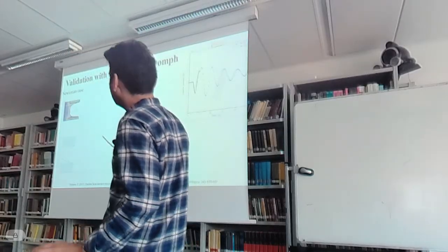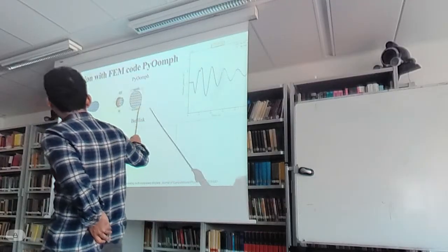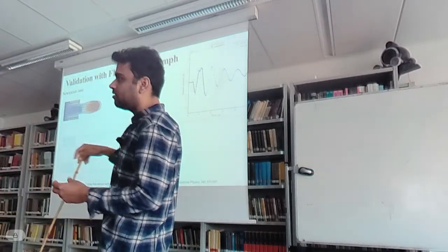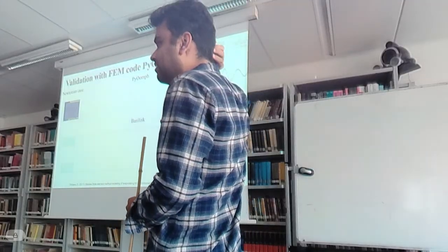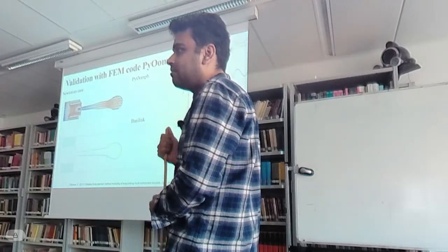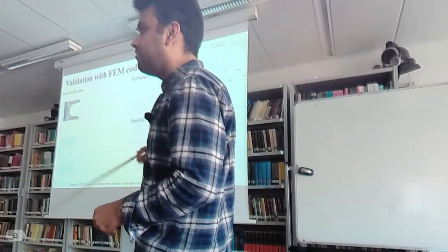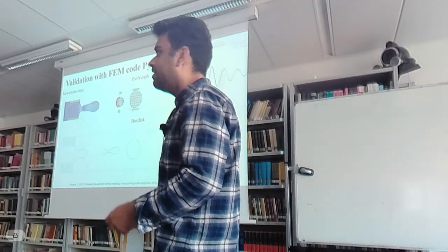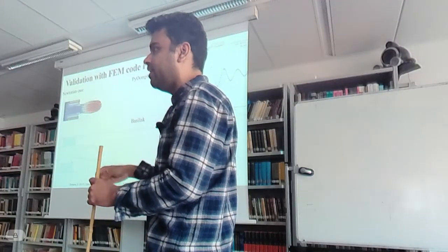But in these simulations you will see that outside, he has assumed that there is a vacuum. So you have a slower jet, and when these merge, you have here a drop, a bubble inside your drops, where there are no bubbles and things like that. So these intricate details, they can do two-phase, then they become slower, and they are faster with respect to time stepping, etc., because they have an implicit method. But the problem is that they cannot do MPI, and sometimes they have problems with breakup also, because they have to break the finite elements.